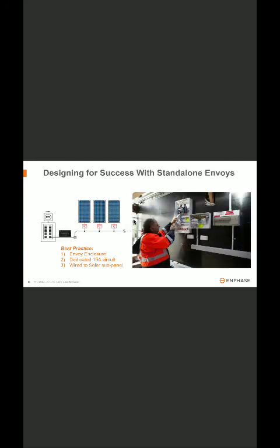In some situations, for example here, there is no PV load center, and the solar breaker lands directly on your main load center. If this is the case, and you find it cost prohibitive to install a PV load center, the next best way to install the Envoy is to install a dedicated circuit specifically for the Envoy.